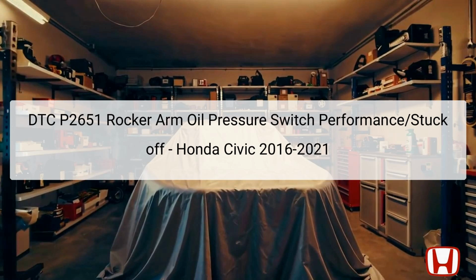Located near the rocker arm oil control valve, this switch detects oil pressure and relays essential information to the powertrain control module (PCM). The proper functioning of this component is integral to the VTEC system, as it ensures that the correct oil pressure is maintained for smooth engine operation. A malfunction could lead to decreased engine performance, increased emissions, or even engine damage.